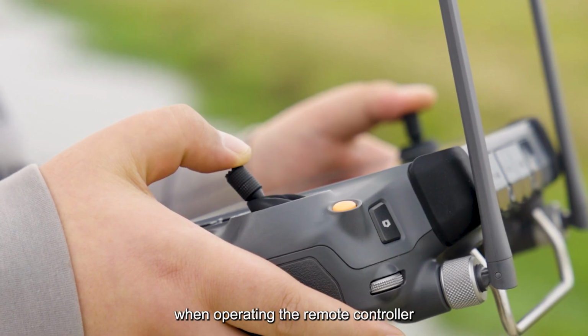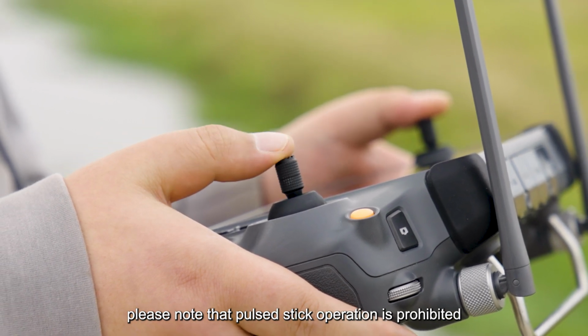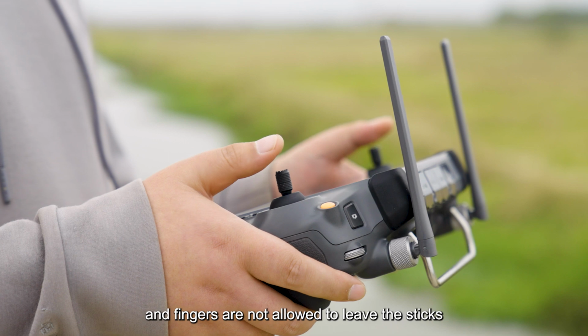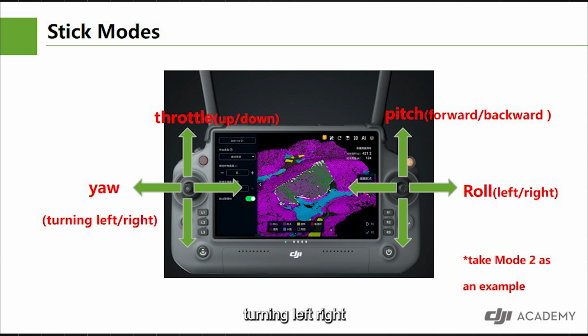When operating the remote controller, please note that pulsed stick operation is prohibited, and fingers are not allowed to leave the sticks during manual flight. The left and right sticks can be moved in up, down, left, and right directions respectively, with the corresponding 4 actions of the aircraft: flying up, down, turning left, right, flying forward, backward, and left-right lateral movement.